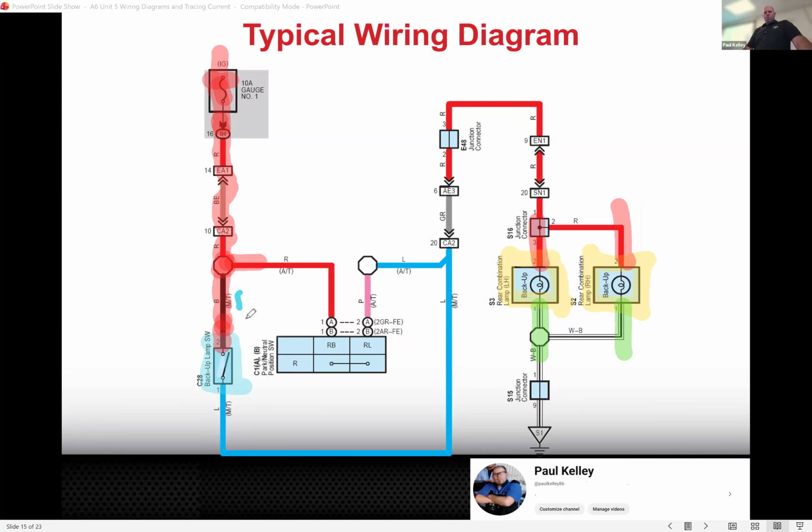Currently, we won't have any voltage down here. Do you know why? So what should we do to test the backup lights? How do we close the switch? In this case, how does the vehicle know you're in reverse? You have to actually click the shifter into reverse. When you move that shifter in reverse, it moves a rail in the transmission, and the rail pushes on a little switch.